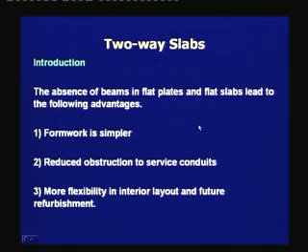The absence of beams in flat slabs and flat plates leads to the following advantages. First, formwork is simpler. Second, reduced obstruction to services.